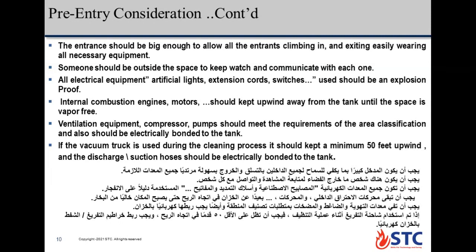All electrical equipment, artificial lighting, extension cords and switches used should be explosion proof to prevent the fire risk.